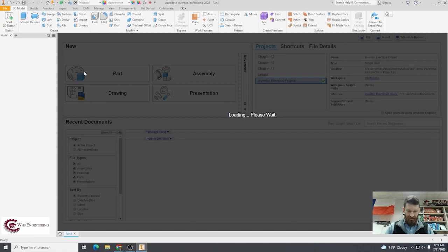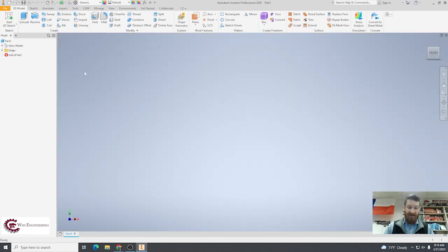And the general procedure here is pretty simple, right? You can find this on page 3 of Chapter 2. Number 1, create a rough 2D sketch. Number 2, apply constraints and dimensions to clean it up. Number 3, extrude, revolve, or sweep that parametric two-dimensional sketch. Number 4, add additional parametric features as you go along. Number 5, refine the design as needed. And number 6, create the desired drawing views.